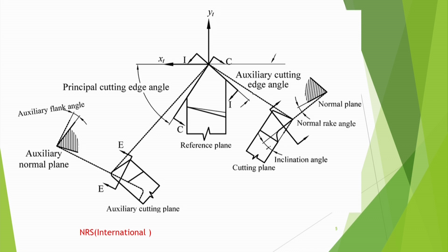So the normal rake angle can in that case be called the true angle. So sometimes, if you want to do analysis, the normal rake angle system is better. In the normal rake angle system, whatever normal rake you have got can be called an approximate rake angle, and you can use that even in the orthogonal formula.